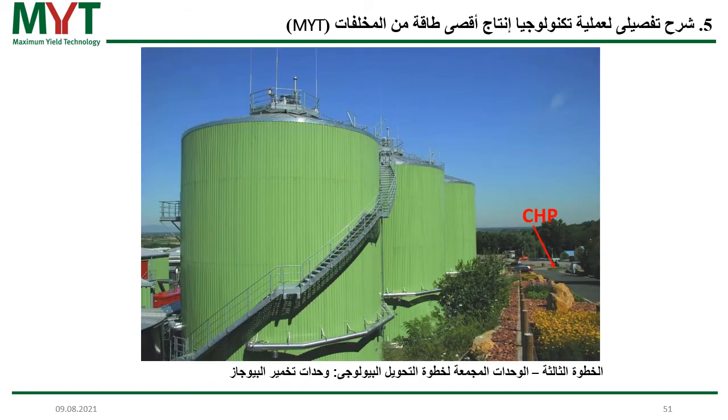So the press water, like I told you, is going to the biogas fermenters. And we have here 3 biogas fermenters, 2,000 cubic meters of volume. The process water stays in one fermenter approximately only 10 days. So that shows you how fast this process is. Because if you put solid material, if you put bio-waste into fermenters, you need 23, 30, 40 or even more days for the biogas conversion.